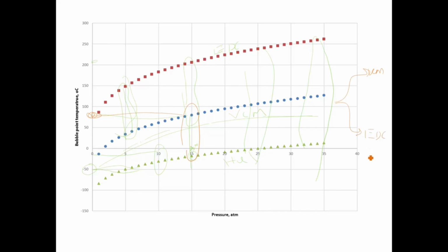So we are going to check what should be the reboiler temperature for that to happen, and what should be the condenser temperature in order to collect VCM as a liquid in the top, and what should be the reboiler temperature required to vaporize this particular component. Okay, so again we are going to use the same set of procedure. We will add a component splitter, followed by the shortcut distillation column, and then we will do the rigorous distillation column.